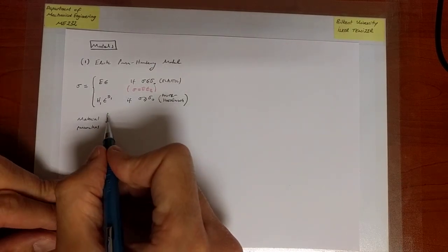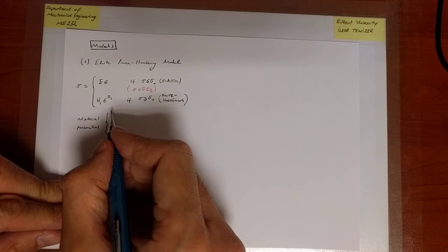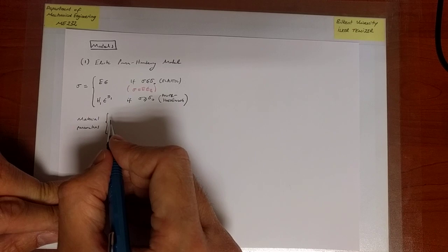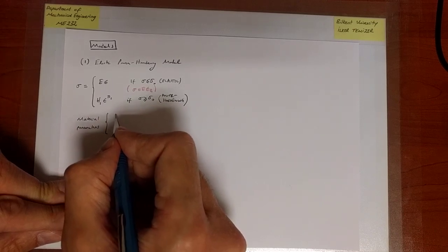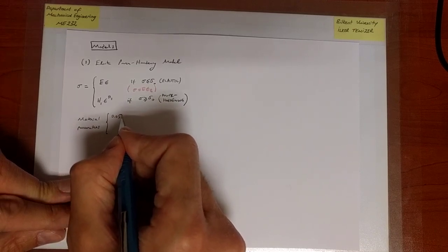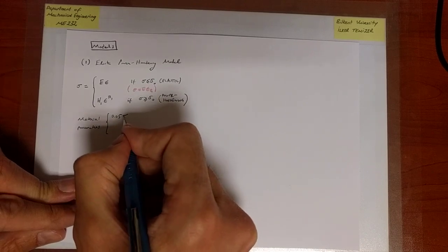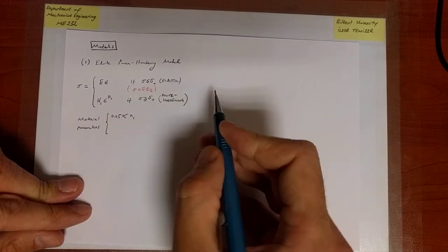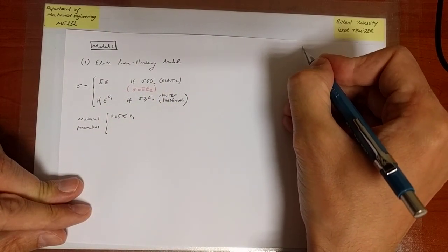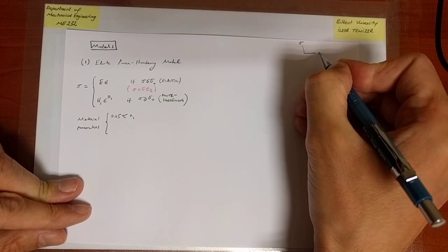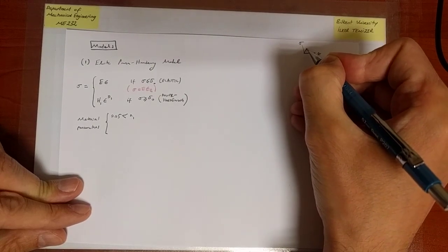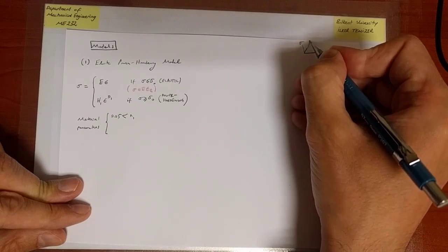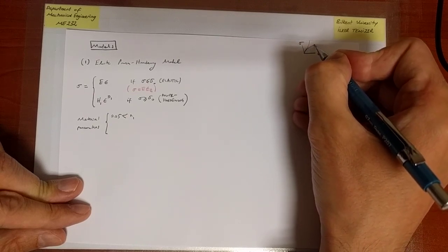I'm going to solve a simple example. Well, this example is not simple, but I'm going to solve it in a simple manner to demonstrate the idea of the determination of these parameters. So first of all, let me mention that the parameter that we have, the exponent n1, obviously, first of all, is something that is less than 1, right? So if I want to write a relation between stress and strain beyond the point of yielding, if the exponent is larger than 1, the curve will go like this. If it is less than 1, it will go like that.